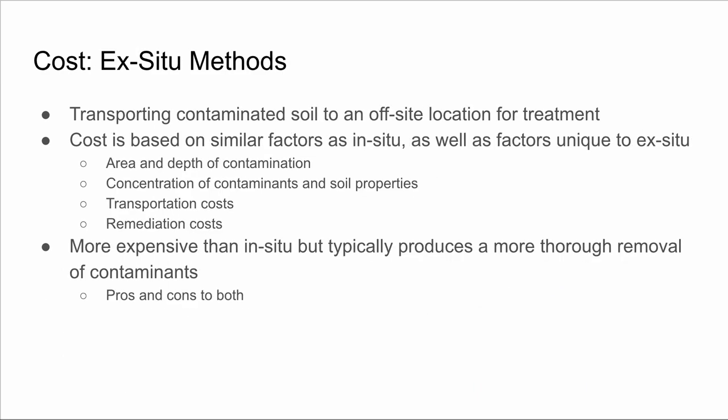Okay. And then on the other hand, you have ex situ methods. I won't cover this as much or nearly as in detail, but this is where you're taking the soil to an off-site location for treatment. The cost is based on many similar factors to in situ, and then it has a couple of its own. So area and depth of contamination and concentration of contaminants in soil properties, those are all very, very similar to your factors for in situ, so I'm not going to cover those. But your biggest additional costs with ex situ come from the transportation. So moving dirt is expensive.